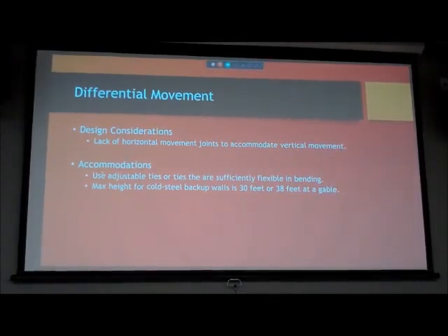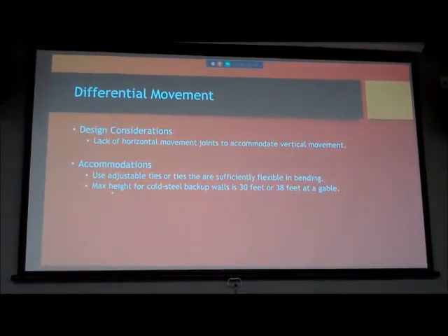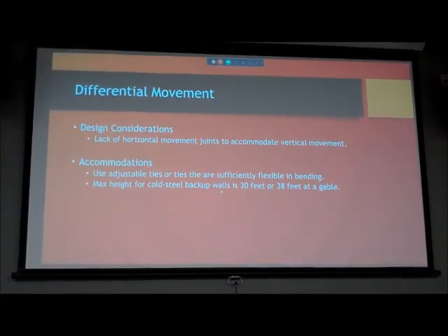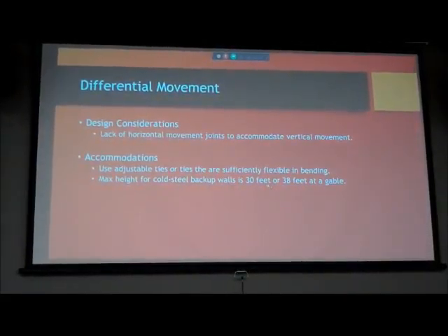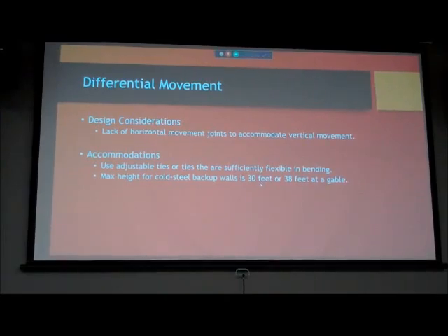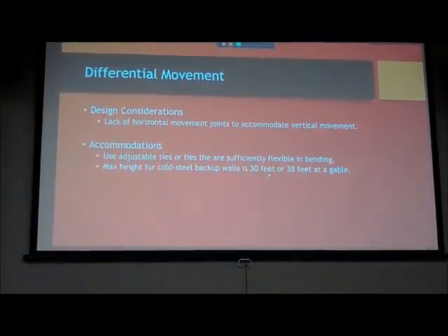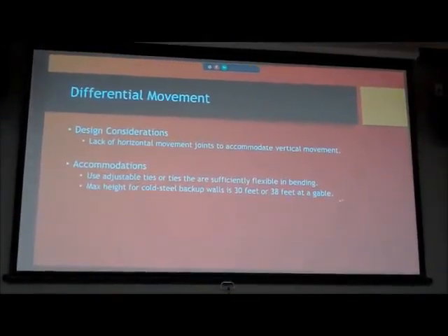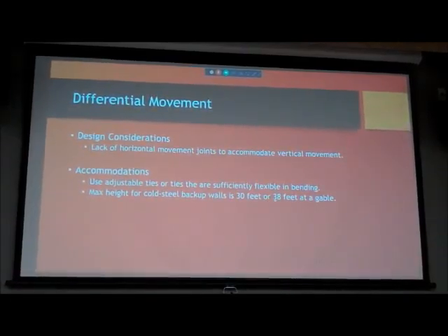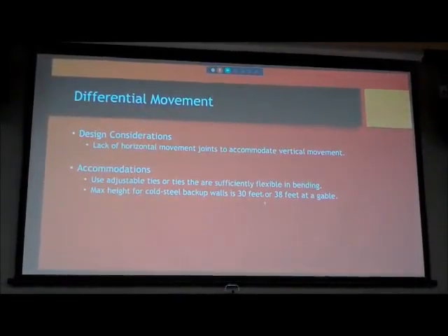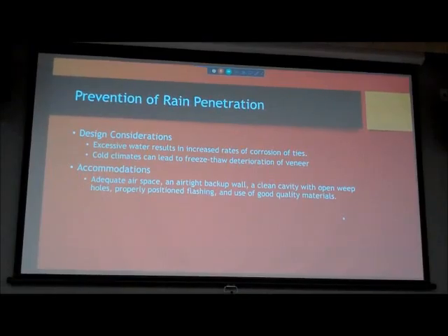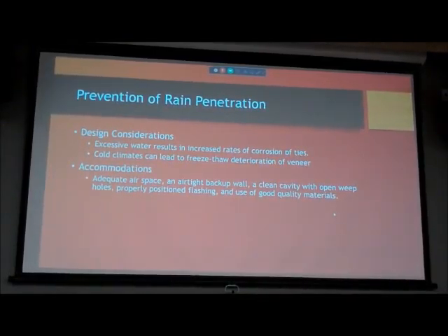Also, don't make the backup walls more than 30 feet tall over the foundation. The exception to that is at a gable, where it's 38 instead of 30. Remind me to comment on that. Okay.